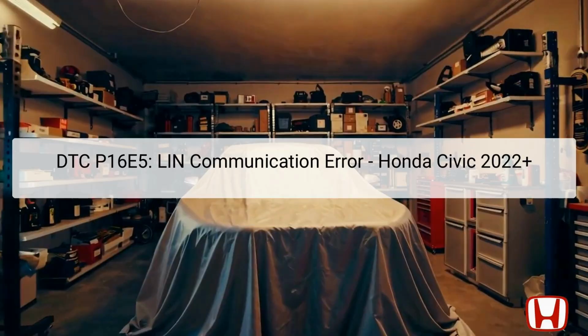The Diagnostic Trouble Code, DTC P16E5, is associated with a LIN communication error, specifically between the Powertrain Control Module, PCM, and the DC-DC converter in the Honda Civic models from 2022 and onwards.